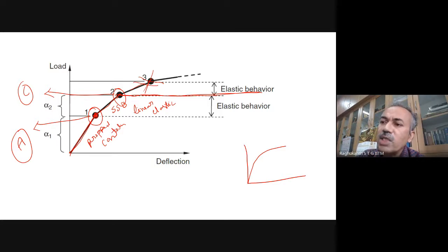Although we are saying it is a plastic analysis, it is something like you are doing it two times. Once a hinge has formed, it becomes another beam, and then once again we are carrying out the same linear elastic analysis, whatever you have studied in your structural analysis. So all that is a plastic analysis, but we have done incremental linear elastic analysis itself.